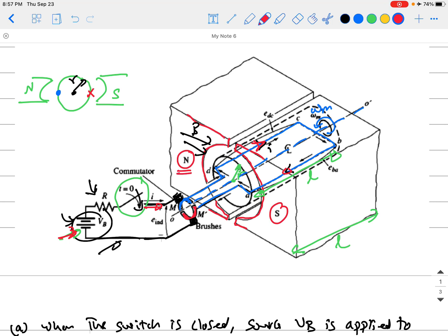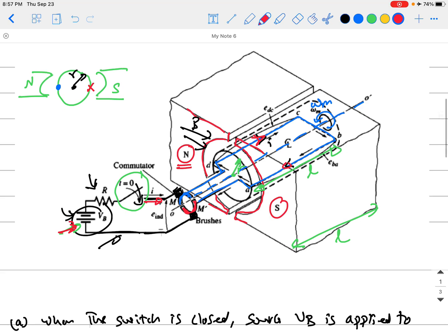So now you have all the conditions to have a motor. So the machine is a motor and it starts rotating. So you now have electric energy converted to mechanical energy, and the motor starts rotating. Yeah, but while the motor rotates, now you have all the conditions for a generator also applied. You have a coil rotating inside a magnetic field, so induced voltage will be created on this coil. So keep this in your mind: in each motor you have inside the machine a small generator, another generator inside the machine itself.